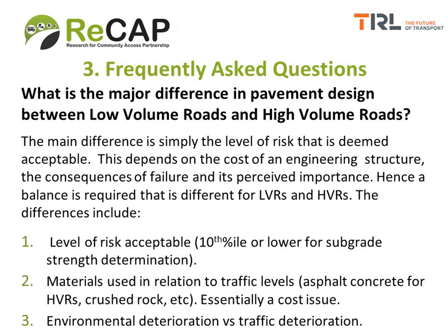And as we know, for example, with our drainage design, for the more expensive structures, we design for the much rarer but stronger storms. The same sort of principle applies to the road structure. So basically, a balance is required. The low volume roads are not as expensive as high volume roads. Therefore, essentially, you can normally accept a slightly higher risk.